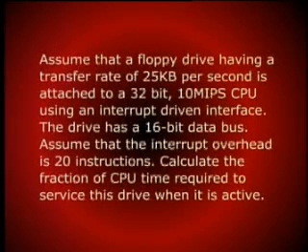In the next example, we see different devices connected to the same bus using interrupt. The example reads: assume that a floppy drive having a transfer rate of 25 kilobits per second is attached to a 32-bit 10 MIPS CPU using an interrupt-driven interface. The drive has a 16-bit data bus. Assume that the interrupt overhead is 20 instructions. Calculate the fraction of CPU time required to service this drive when it is active.